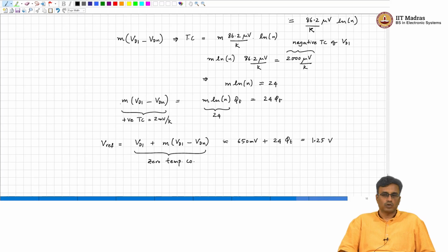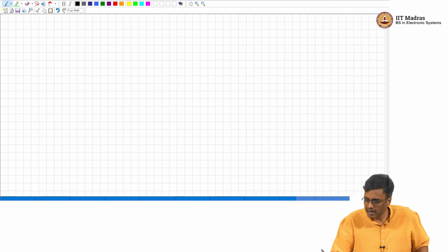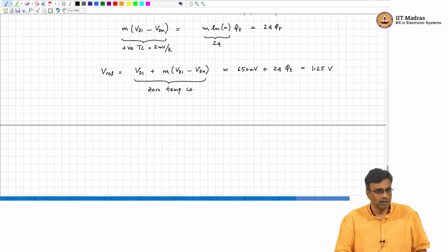Okay. So, it so turns out that if you go deeply into the physics of the bipolar transistor, you can trace this reference voltage down to the band gap of silicon, because it has got things in it which depend on the silicon band gap and so on. So, the bottom line is that this reference can be traced to the band gap of silicon, all right.